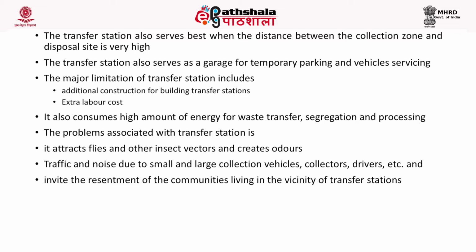The problems associated with transfer stations include that they attract flies and other insect vectors and create odor because they act like a temporary storage site. Also, traffic and noise are created when vehicles enter the transfer station for unloading and reloading. Third, it also invites resentment from the communities living in the vicinity of the transfer stations.